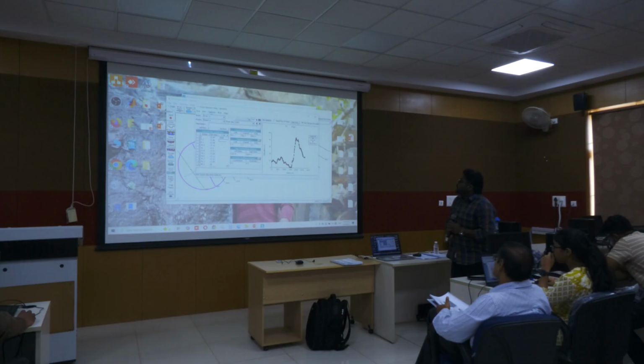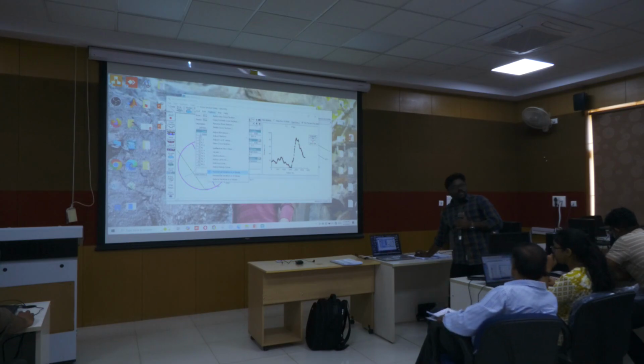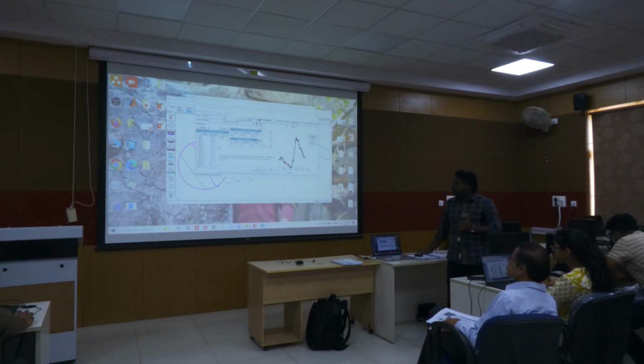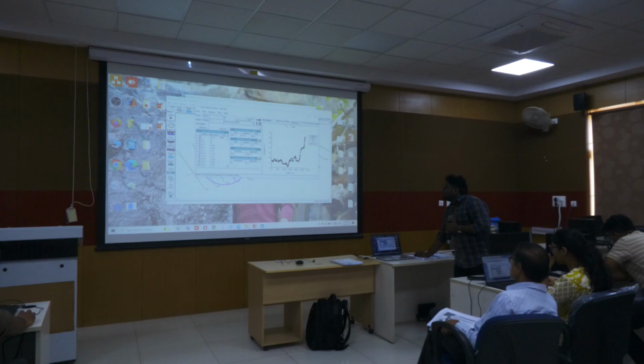See here. There are options. Go to options. Here, horizontal variation in n values. It is enabled. You disable it. So just click yes. So that column will be omitted here. So in the same way, change the cross section. Disable it, like this.